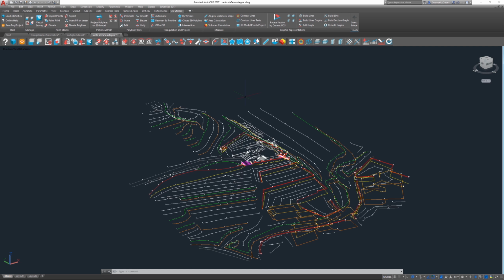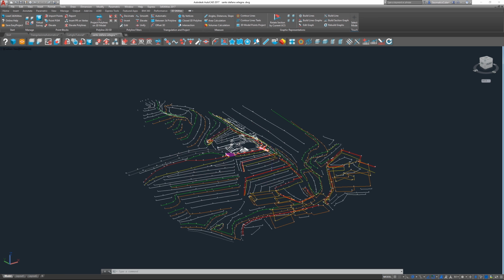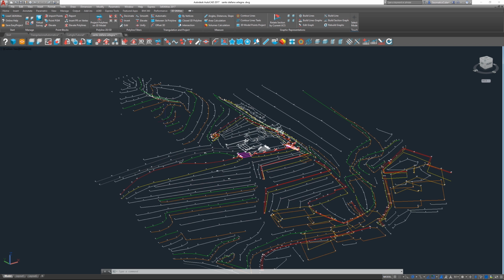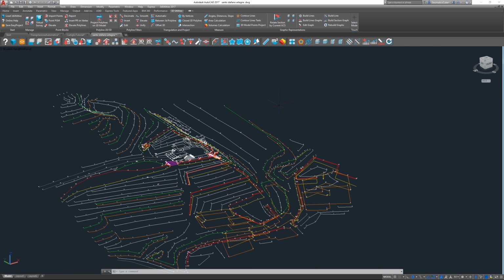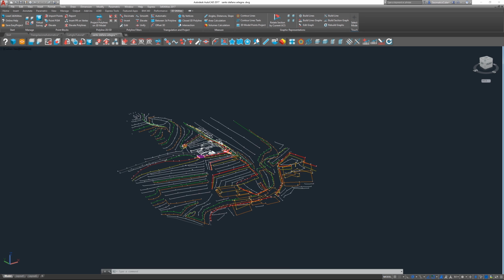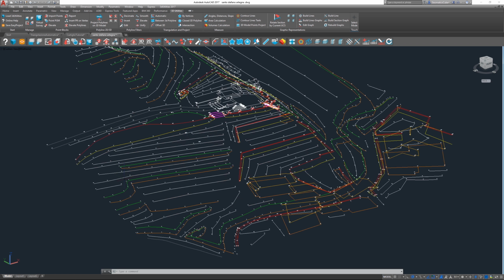Hi, in this video, you're going to see how to create an automatic triangulation inside 3D utilities. As you may notice, we have the same example that we've used when we thought about virtual surveys. I've done this virtual survey over a point cloud. I've drawn my polylines. I've used insert pair blocks to add point blocks over every vertex of the polyline. So right now that I have this material, I'm able to do an automatic triangulation.